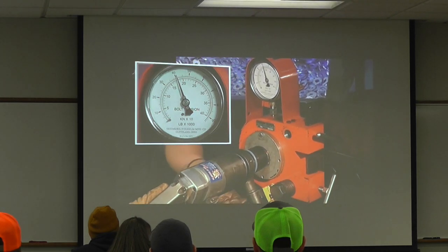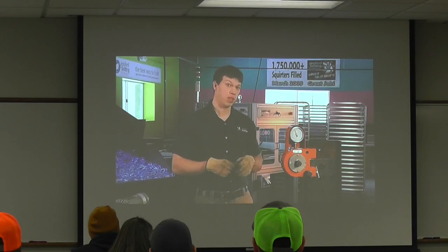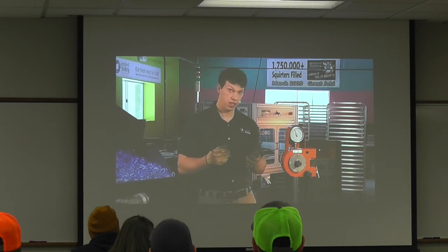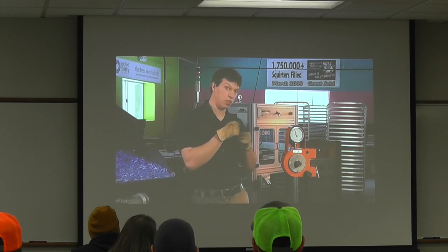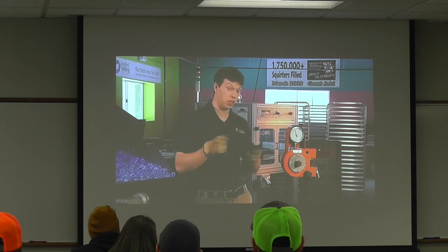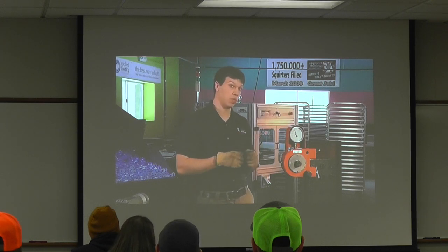There's 41,000 pounds. So now that we've hit 41,000 pounds, we're going to use our 5-thou feeler gauge and see how many entries and refusals we have. Now an entry is where the tip of the feeler gauge goes in and touches the bolt shank. A refusal is where it does not touch the bolt shank, even though it may go in part way.